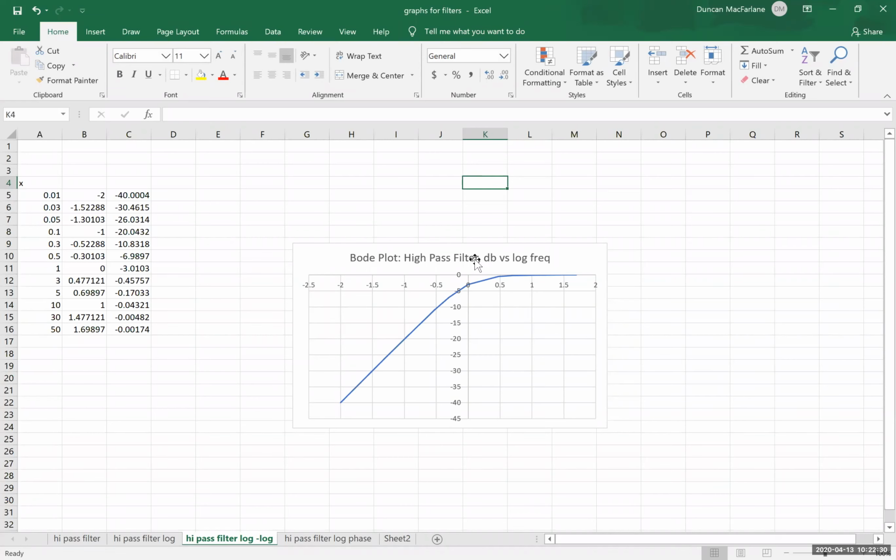And so you'll see that at 0 dB, I have unity gain, and then I roll off at about 20 dBs per decade. The difference between this is 1 decade, 1 order of magnitude, and I drop from minus 20 dB down to minus 40 dB in 1 decade.